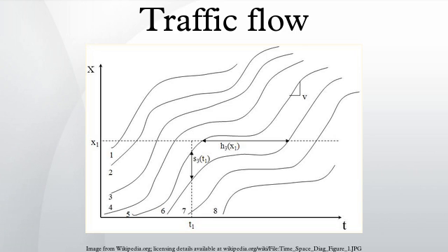2. Two-phase traffic flow models of the GM model class fail because traffic breakdown in the models of the GM class is a phase transition from free flow to a moving jam. In a traffic flow model belonging to the GM model class, due to traffic breakdown, a moving jam appears spontaneously in an initially free flow at a highway bottleneck. In contrast with this model result, real traffic breakdown is a phase transition from free flow to synchronized flow, rather than a moving jam. Due to traffic breakdown in real traffic, synchronized flow occurs whose downstream front is fixed at the bottleneck.